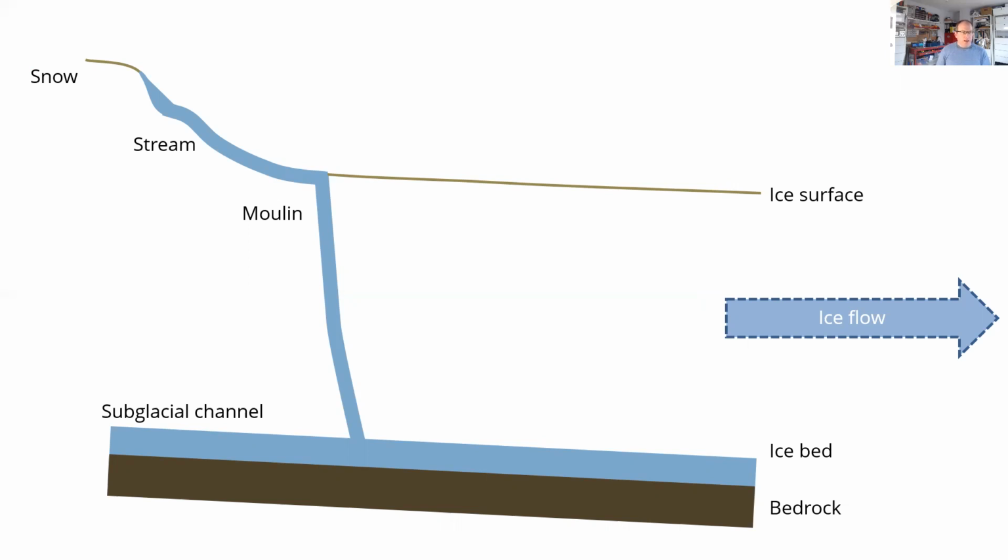And the idea is that we would love to know what's going on in each of these locations. So I'd like to have instruments that measure the conditions within the snow. I call this the smart snow stake. It's sort of like a traditional snow stake, but with electronics built into it that will tell you the snow level and also the electrical conductivity within the snow, which tells you whether the snow is wet or dry and helps you establish the onset of the melt.